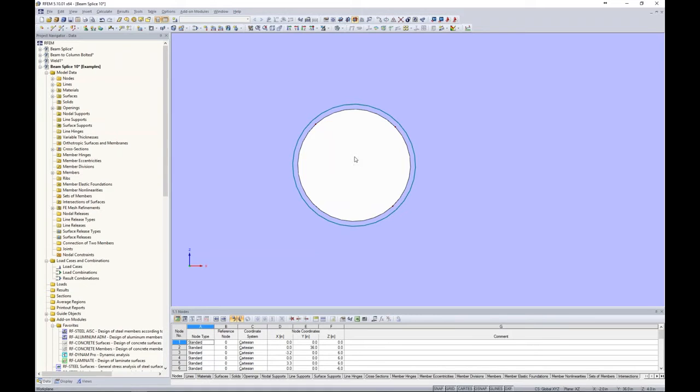Now, those bolt members we'll get into in just a minute, but what they're going to do is frame into the center of these openings. They're 1D member elements, so the question is, how do we connect those 1D member bolts right here in the center to the rest of our plate surface? Well, the answer would be small little rigid links.